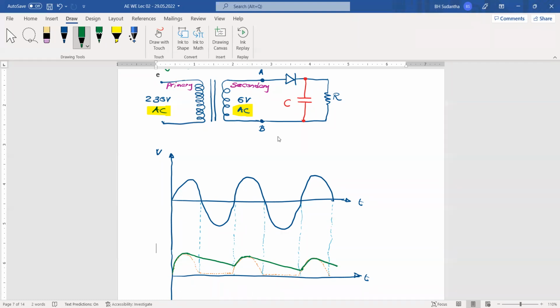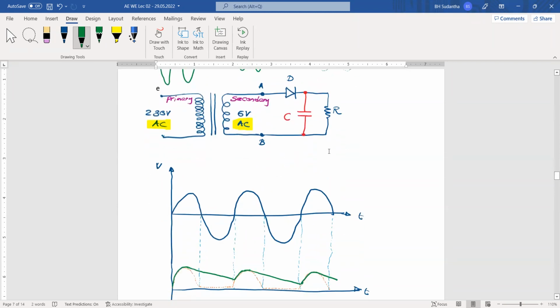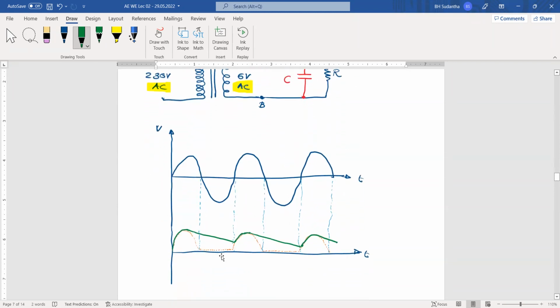it goes like this. Now, when you compare with the previous voltage, only positive half cycles are there. During the negative half cycle, we don't have any voltage, the output voltage is 0. But after adding this capacitor, what has happened? During the blank period, we have a certain voltage.